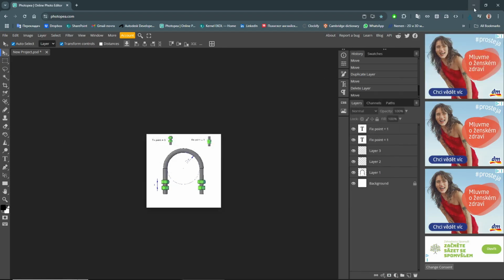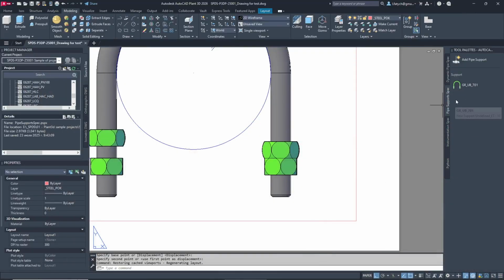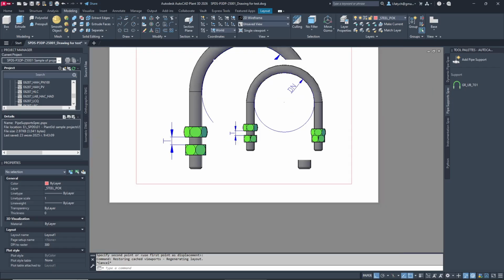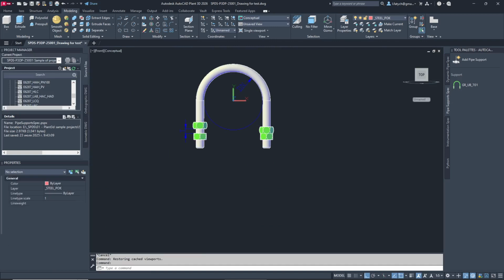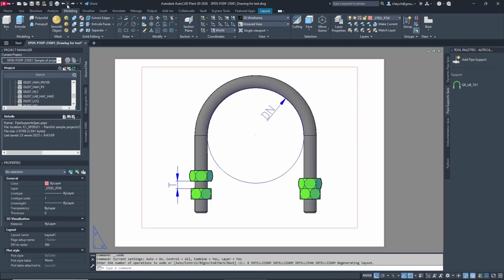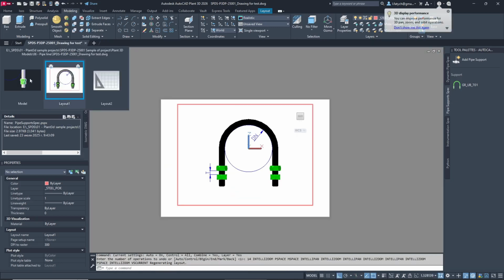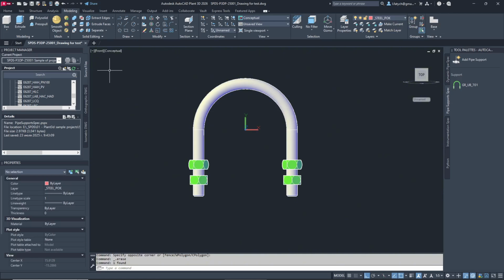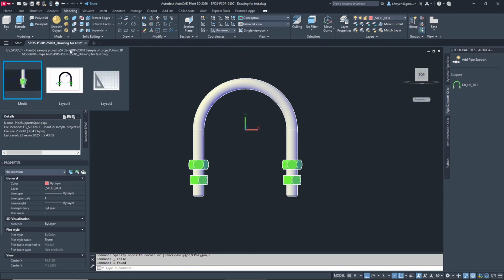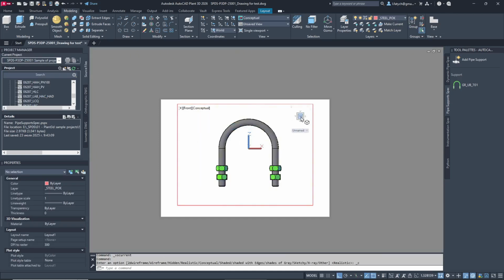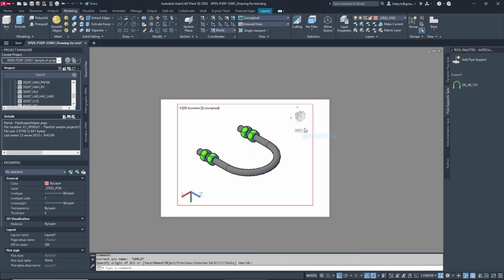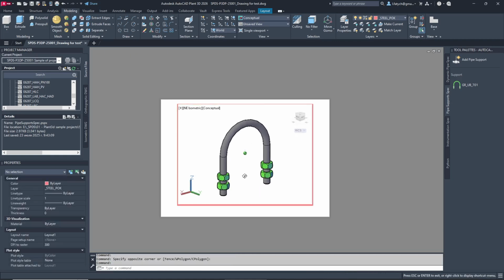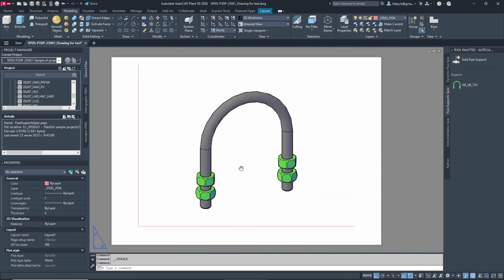Okay. So what we need next, we also need a preview image without dimensions, just clean geometry. So what I suggest to do, let's go to model space and undo the last changes with the moving of the second node to have it in the previous version. Let's delete all the dimensions. Okay, switch again to layout space. We have to select the conceptual view style again, and let's rotate it maybe to look more 3D. You can position it however you like. Okay, it looks good.